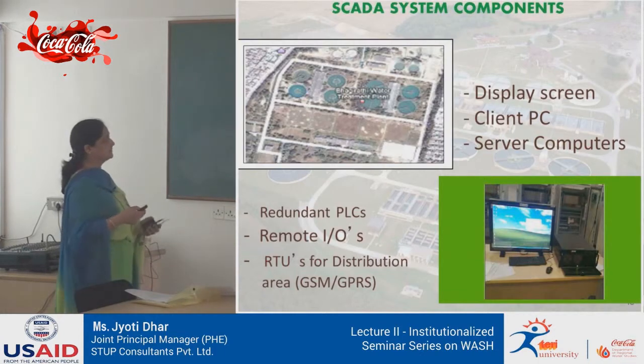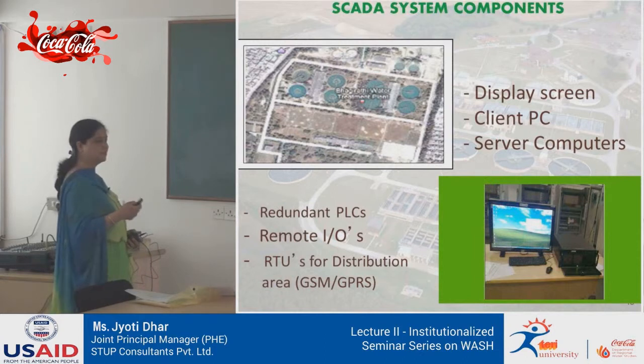These are the SCADA system components. Basically, it's a display screen. You have a client PC, you have server computers, you have a redundant PLC system, you have remote IOs at various locations of the plant. Then your RTU, that is remote terminal unit, at the booster pumping stations or at the distribution areas.